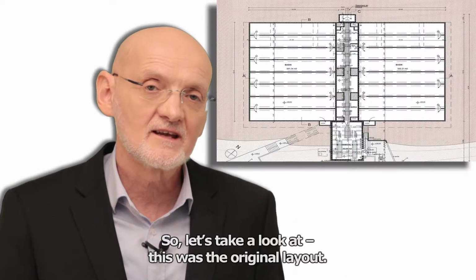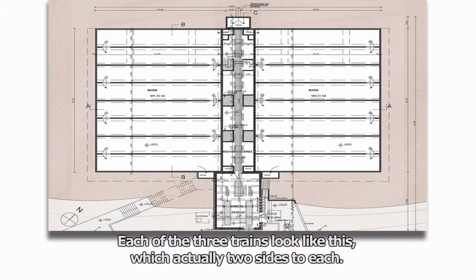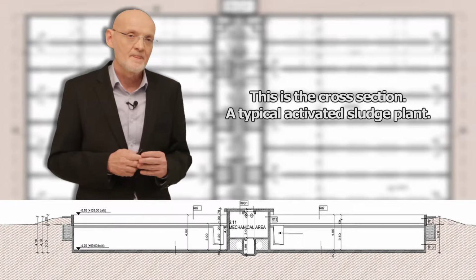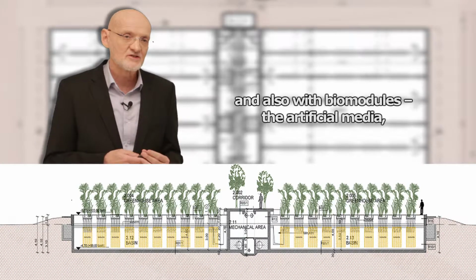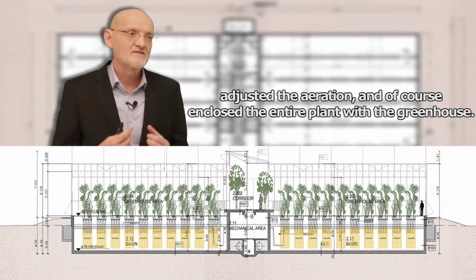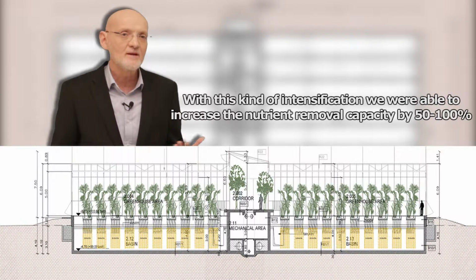So let's take a look at this was the original layout. Each of the 3 trains looked like this, which actually has 2 sides to each. And this is the cross-section, a typical activated sludge plant. And what we did, we filled the reactors partially with natural media, which is the plants, and also with biomodules, the artificial media, adjusted the aeration, and of course, enclosed the entire plant with the greenhouse. With this kind of intensification, we were able to increase the nutrient removal capacity by 50 to 100%.